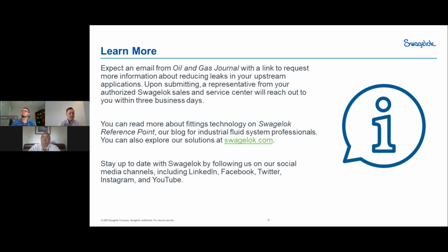All right. Someone asked, which O-ring seal materials would you recommend for carbon dioxide valves that interface with the atmosphere, such as relief valves? Yeah, I can take this one, Matt. Please do. That's a difficult application for sure. We've had some experience with a variety of different compounds. Hydrogenated nitrile butadiene rubber seems to work well.